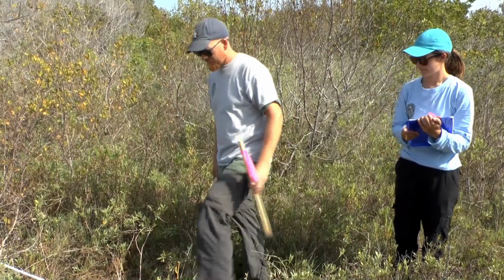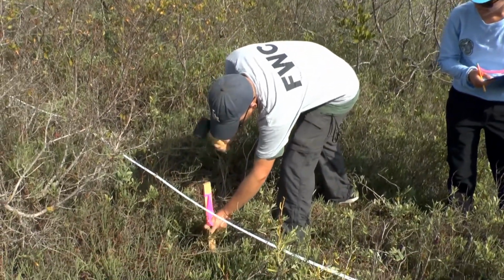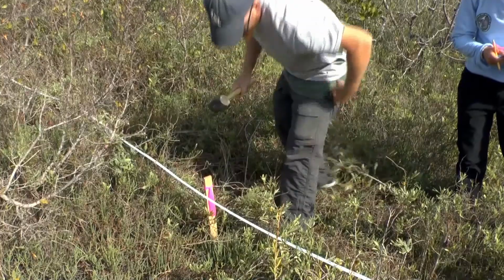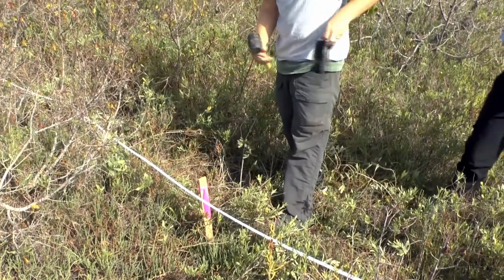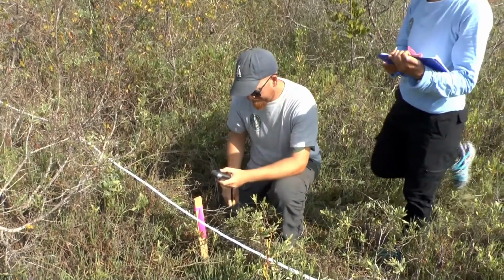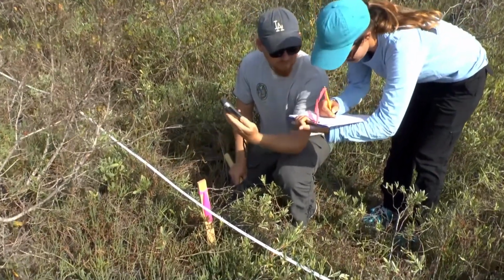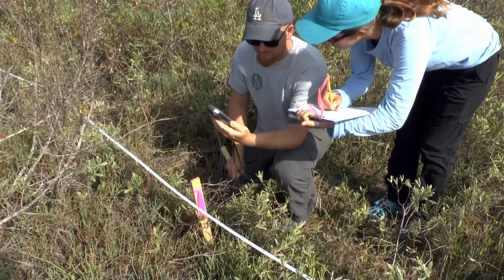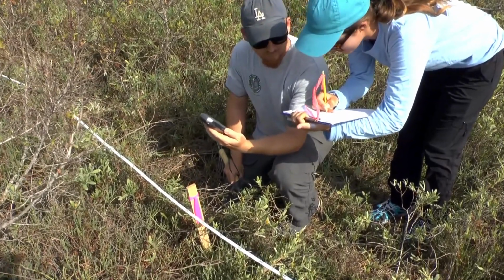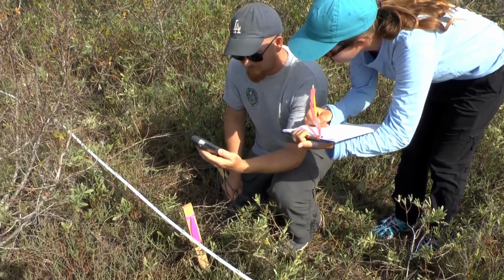Install a physical marker such as a PVC marker or wooden stake at each transition and record the latitude and longitude. These marked locations will also provide a visual aid while extending the transect tape on return trips to the site. Assign each zone a letter and a name and record the width of each zone. Include at least 10 meters of upland habitat at the end of the transect, as this region may shift to high marsh vegetation in future years.